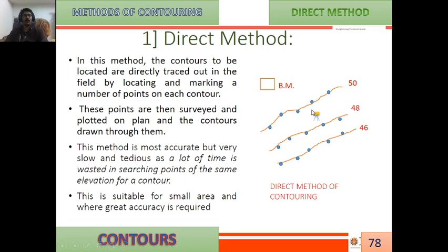So the height of instrument minus x must be equal to 50. So that staff reading must be seen wherever it occurs.